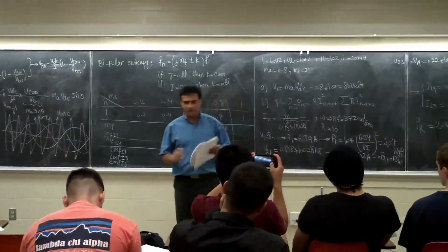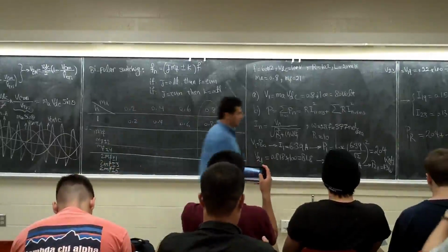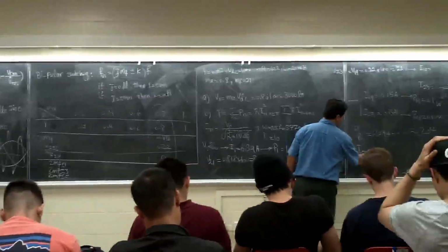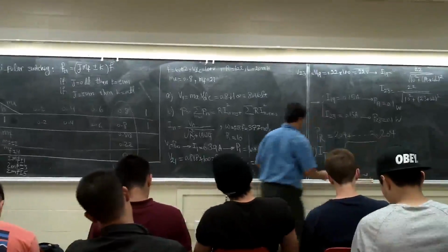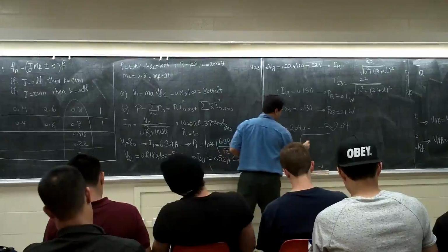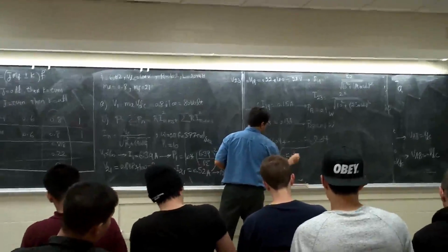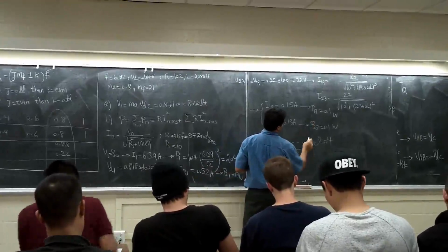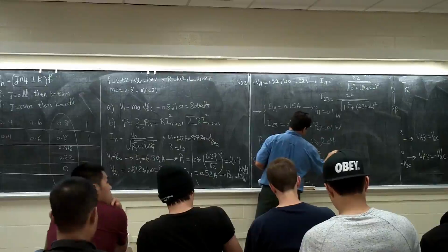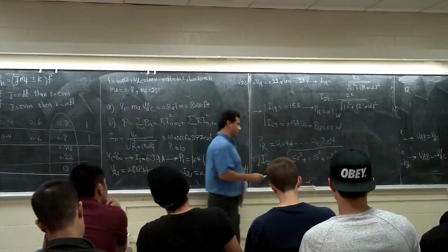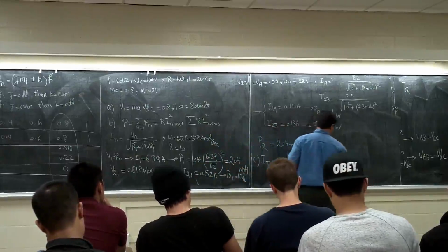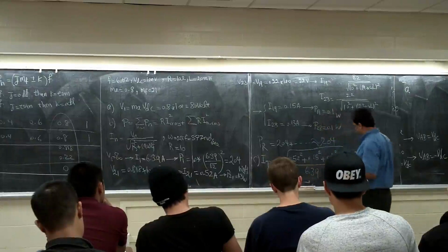The last part is asking how much is the THD for the current, ITHD. See. How much is the ITHD? The non-fundamental, 0.52 to the power of 2 plus 0.15 to the power of 2 plus 0.13 to the power of 2. We're not calculating the rest, right? Divided by how much? 6.39 times 100 is going to be 8.7%.